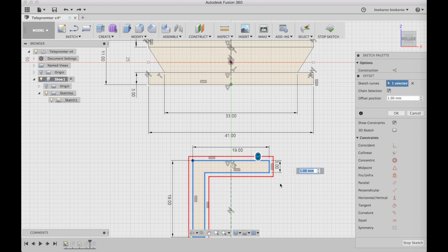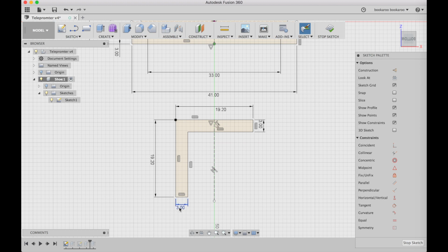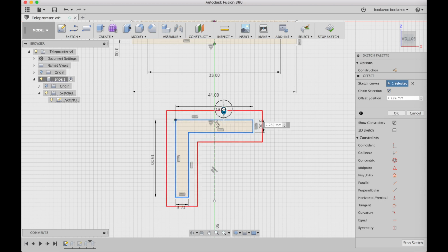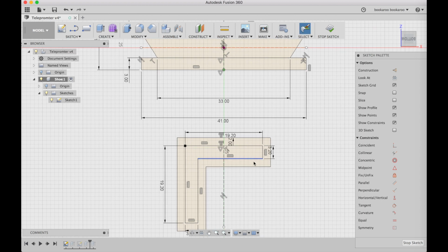But at first I have to do the walls. I realize here that I didn't do the walls, so I'm gonna add some spacing for the angle, so 0.2mm more to have some room, and then do a 2mm wall, and then that can be collinear to the first part.